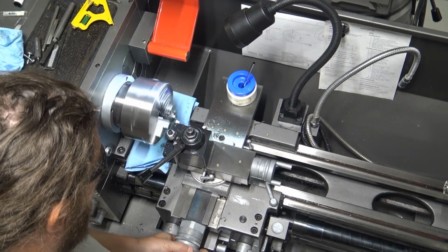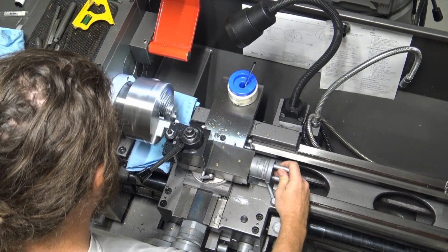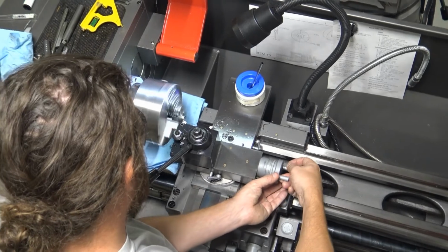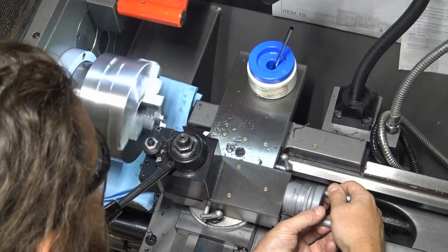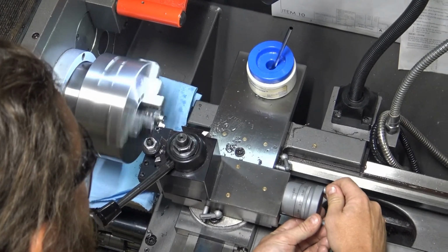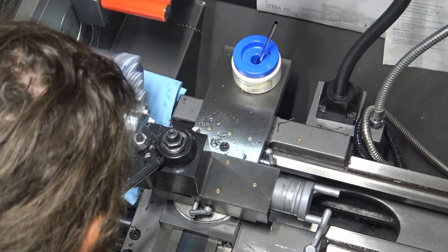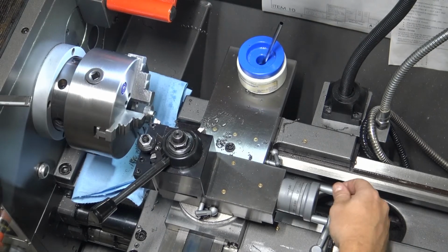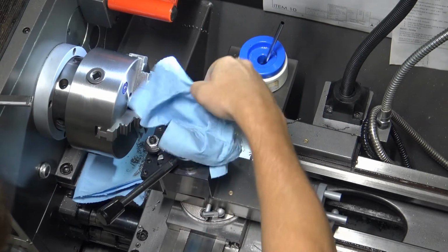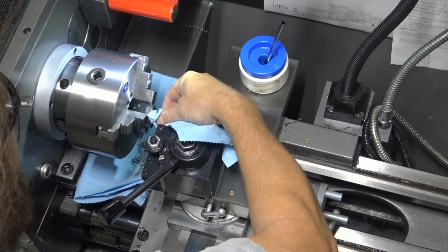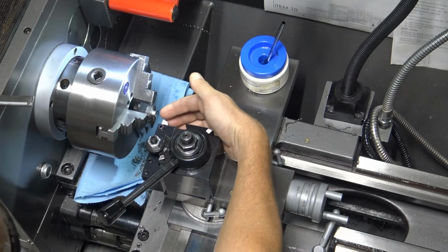All right, I'm out in front of the part. I'm moving another 100 thousandths. Going to the Z depth of 180. All right, and straight back out. So I'm going to move my tool a little out of the way, because now what I should be is somewhere right around 400 thousandths on the diameter of this boss.